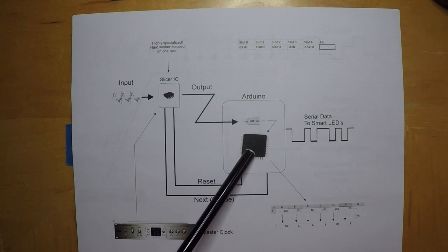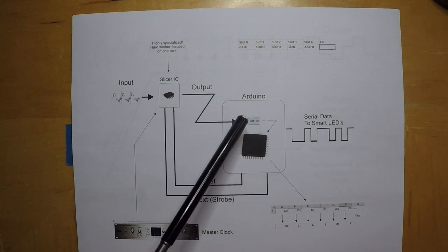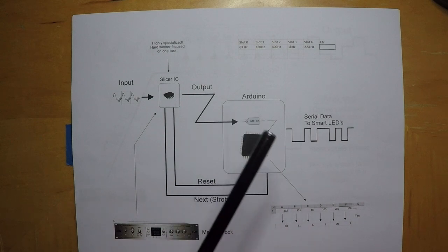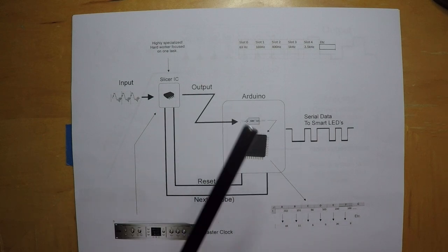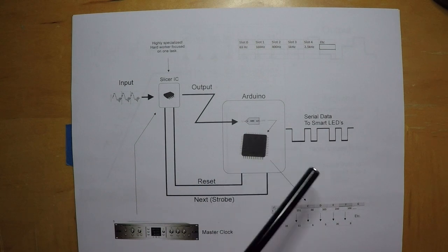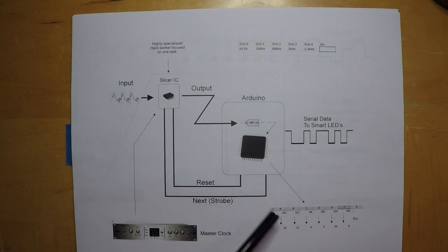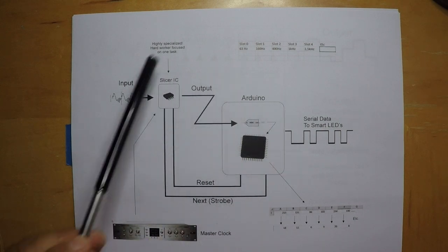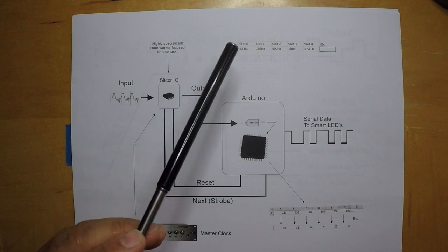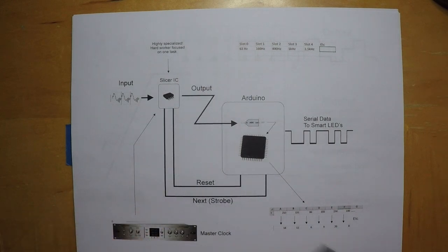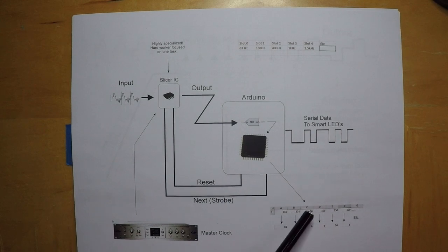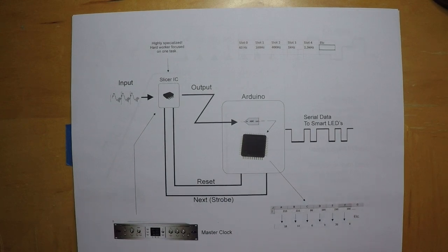This chip is converting that 0 to 5 volts into a binary number, which will be binary 0 up to binary 255. And it stores, for each iteration, each time it goes through that loop of slot 0 to slot 6, it will take those binary numbers and store them in a table. All right?